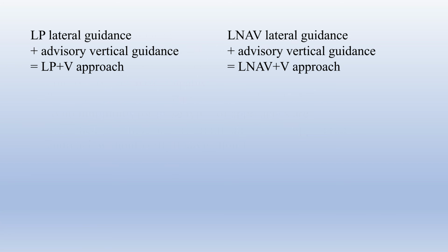The two different types of approaches you can have when you're using advisory vertical guidance: LP lateral guidance plus the advisory vertical guidance creates an LP+V approach. And then LNAV lateral guidance plus advisory vertical guidance equals an LNAV+V approach.